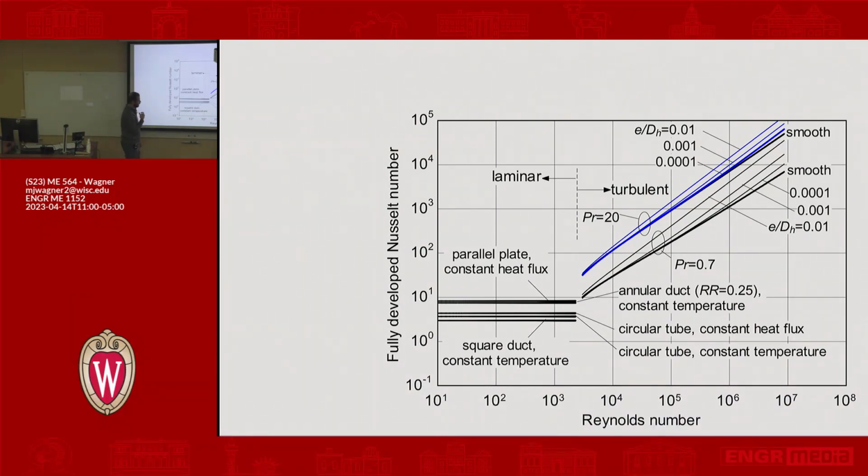We know that the turbulent Prandtl number dominates the heat transfer. But if we look at the temperature gradient in the viscous sublayer, what is that temperature gradient limited by? It's the molecular properties in the viscous sublayer, where there are no eddies. So the Prandtl number is important to account for when you're looking at turbulent flow. Okay, questions on this?